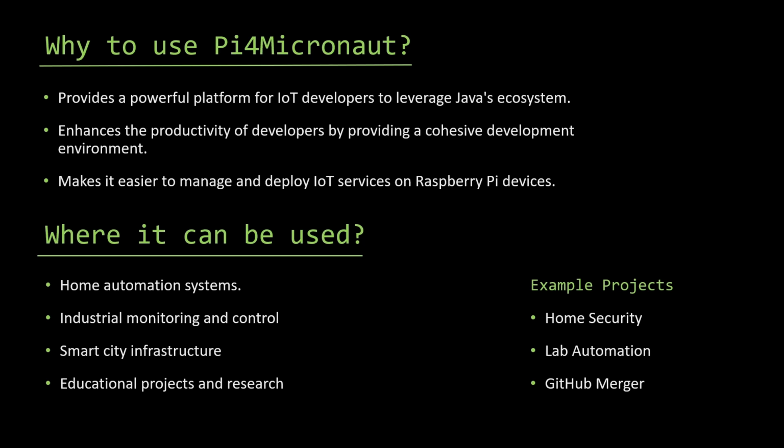And we also developed a lab automation project, which is a mouse maze, where we assumed there will be a maze where a mouse enters and exits through particular points. We have attached two ultrasonic sensors to detect the motion of mice, and we have taken the inputs of start and end time. Based on that, we are calculating how long the mouse took to exit the maze. This is for a research purpose, and we named it lab automation.